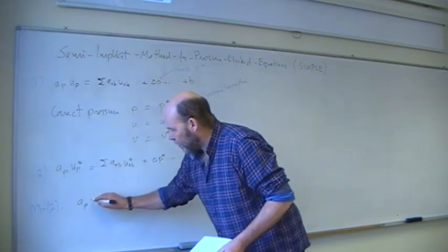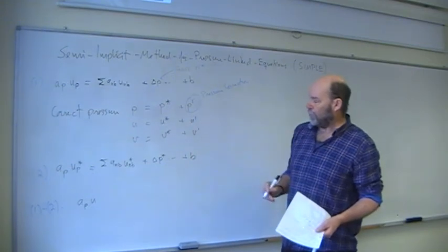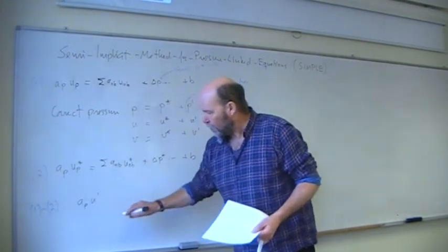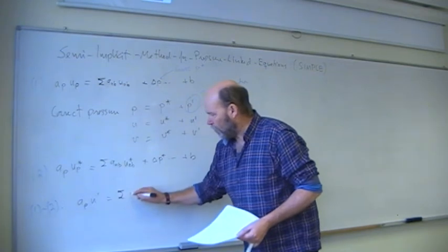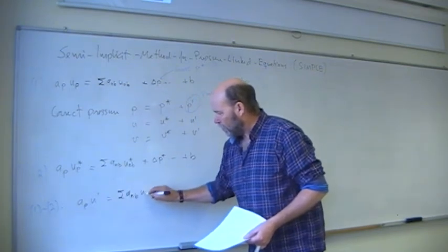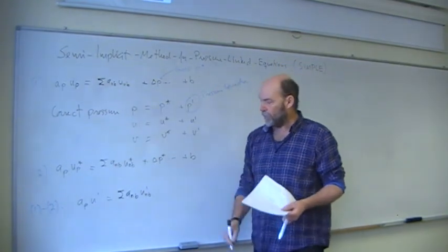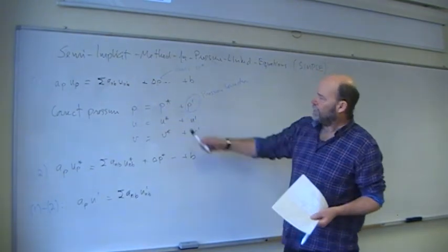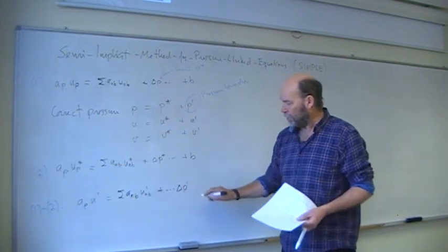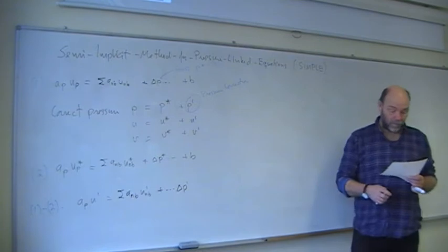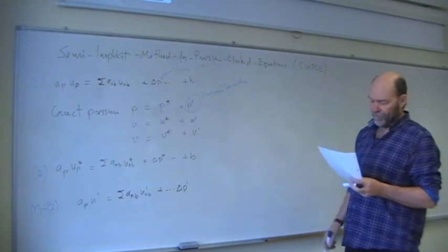Same coefficients, but now the real u minus this u star, meaning we have only the velocity correction. So that's nice. Equals the sum of all the neighbors, u neighbor, and also correction. It's the real one minus the star, so this is quite okay. Same goes with the pressure, plus whatever we have, delta P fluct. The constant B will now disappear. So here we have an equation giving us the velocity correction.